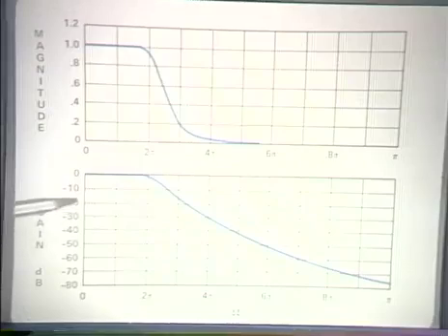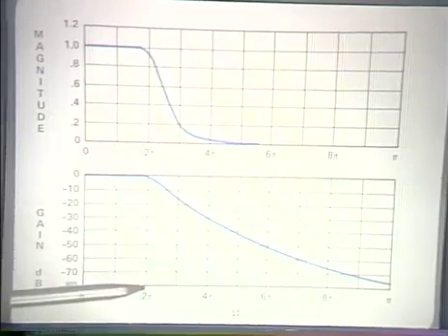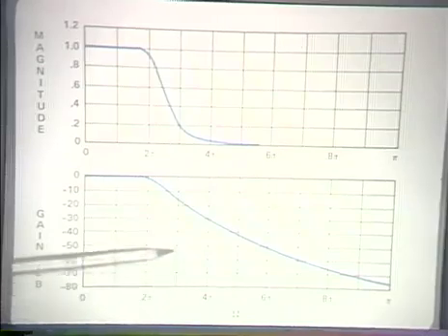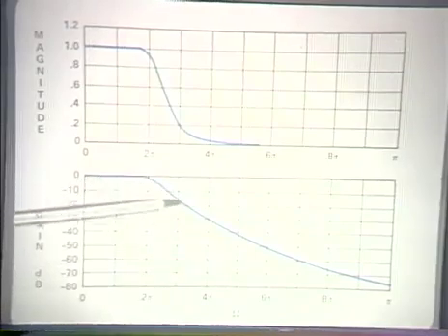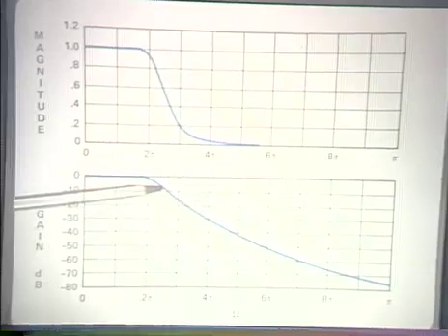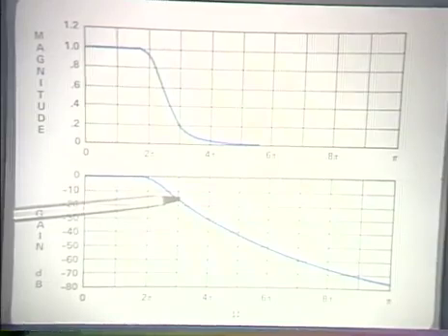And as we had originally specified, the digital filter is supposed to be greater than or equal to minus 1 dB at 0.2 pi and less than or equal to minus 15 dB at 0.3 pi. And in fact, this slightly exceeds those specifications since we had purposely allowed some margin in the stop band.